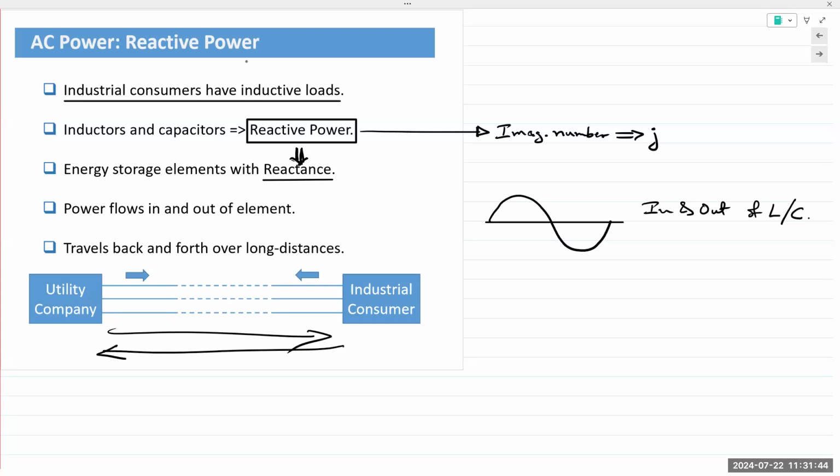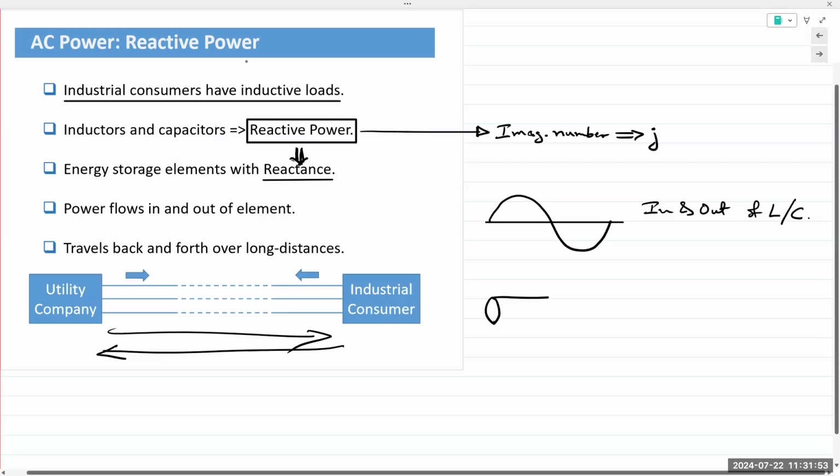And every time voltage or current flows through your wires, there is power loss. A wire, doesn't matter how good of a material it is, has resistance. That resistance is equal to rho L over A. Rho is the resistivity of the material. L is the length of that wire. If this length is hundreds of miles, it doesn't matter how large the area is, basically the cross section of this wire.